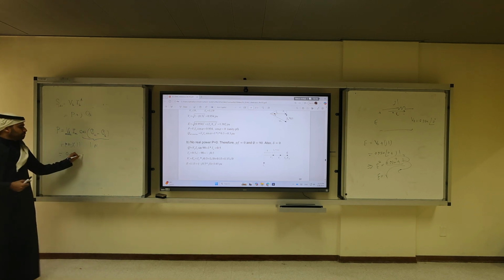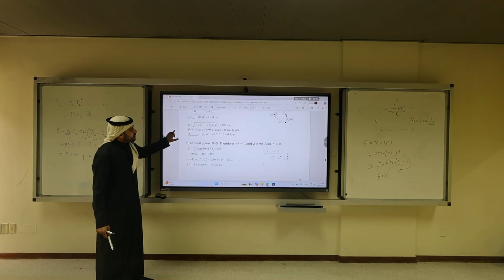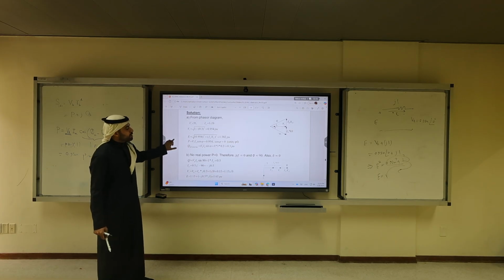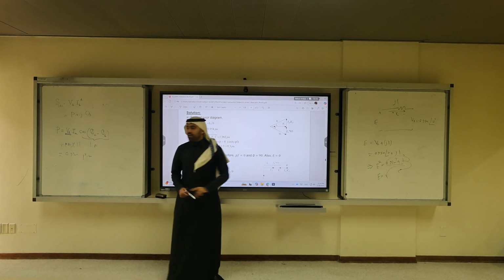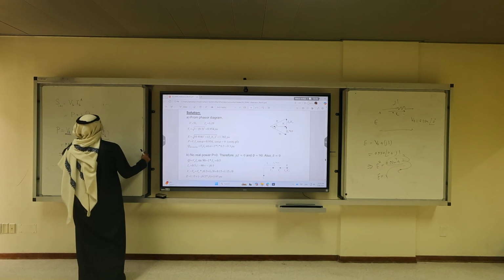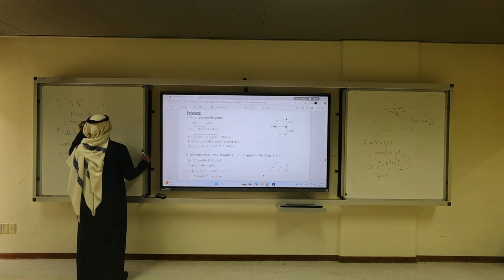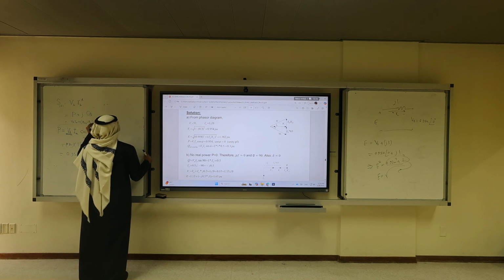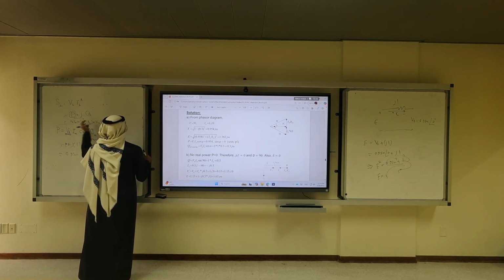This is in watt or per unit? I think it's in per unit. This is per unit of power. To calculate the Q, I need to calculate the alpha. If I want to do real power at the infinite bus, I have to do something like Vb, Ib, cosine of theta Vb minus theta Ib, which is Vb, I'm talking about this P, Ib, cosine of, what is the angle of theta Vb?